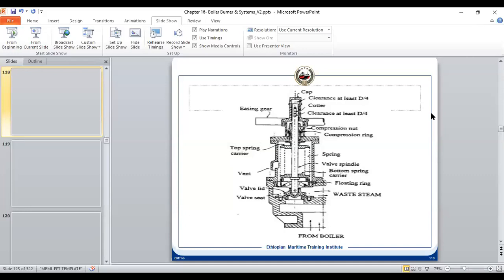But my question is, there is high temperature in the boiler exhaust line, but the reason they give is excessive draft of the ship. Yes, excessive draft of the ship. Yeah, that is what I understood also. If the ship's draft is excessive, obviously the power required to move the ship is also excessive, and the steam requirement is excessive. And if your steam requirement is excessive, you'll have to burn more fuel. So your stack temperature, that is your uptake temperature, can increase.